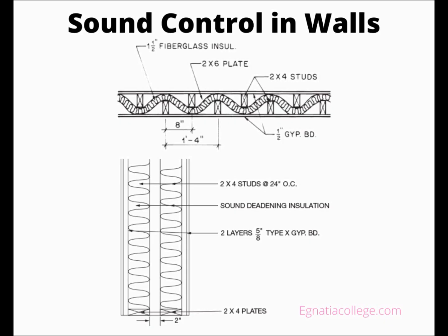Raceways may require installations that reduce sound transmission, such as expansion joints, flexible raceway, or raceway offsetting through the party wall. The STC rating of a wall can be improved greatly by not allowing the studs to contact both surfaces. This may be accomplished in one of two ways. One method is to attach clips made for sound insulation to the studs and then fasten the wallboard to these clips. The clips absorb the vibrations.